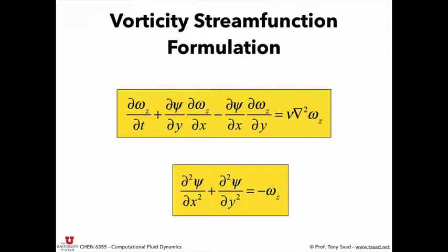So there's uniform flow coming through here. What happens, we know from observation and experiment, is that this is uniform flow. There's equal velocity everywhere, u infinity. Then once the flow hits the boundary, it sticks to the boundary and starts developing a profile like this, where this is still u infinity, but goes to 0 over here, like 90% of u infinity all the way. So now this is one directional flow. And if this is x and y, you only have u as the non-zero component, one direction.